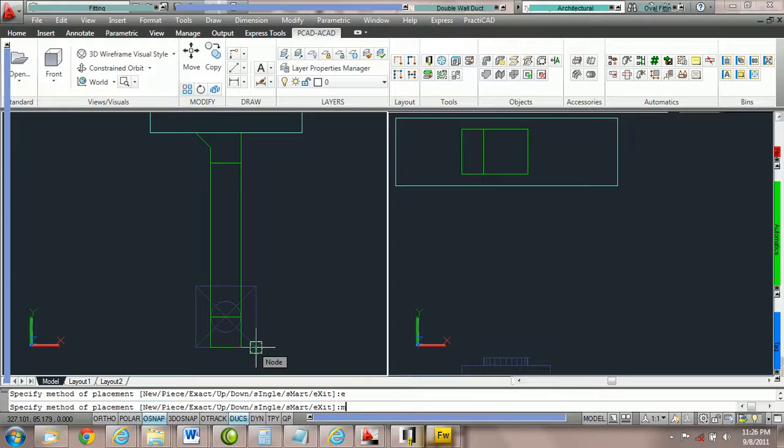I'm going to hit M spacebar. By doing that, it extends the straights. Just like in other tutorials, we extend the straights of elbows, it'll extend the straights of the boot tap and give us full length joints of duct. So here, I can hold my corner point of the grill, and when I click, I now have one boot tap and one piece of rectangular duct. That concludes the tutorials on using the tap parameter box and placing down taps.